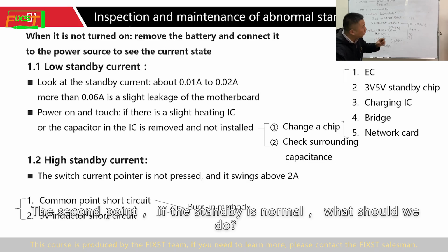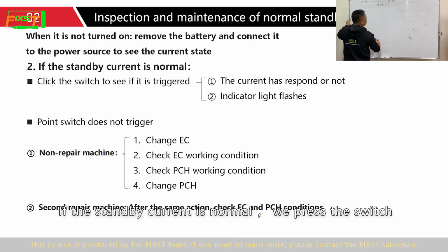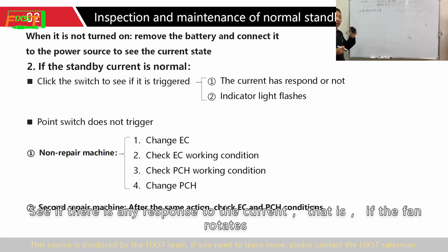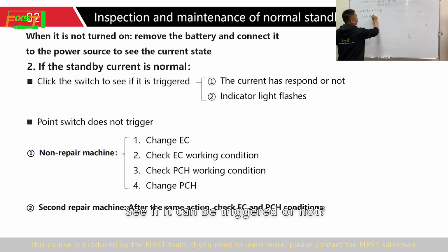The second point: if the standby is normal, what should we do? If the standby current is normal, we press the switch and see if there is any response in the current, that is, whether the fan works, to see if it can be triggered or not.